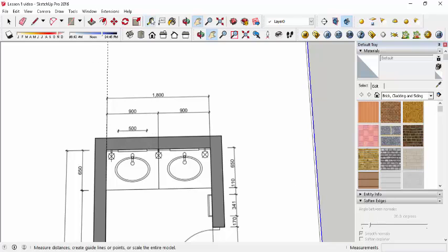So when you click on one tool, let's say if we're using tape measure, click here again from the guideline. When you drag it, while the tool is still on function, just type in the measurement on your keyboard. So either you're using a numeric pad or you're using the numbers on top of the letters on your keyboard. That will do.